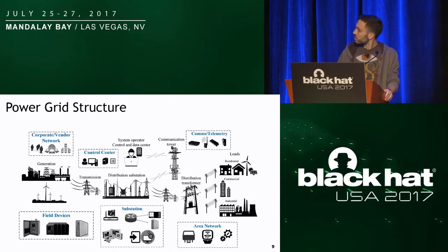The current grid infrastructure is also equipped with cyber systems nowadays that aim to improve the reliability and the efficiency of the grid. These systems include, among others, communication networks, control automation systems, and the so-called intelligent electronic devices that exist in various parts of the grid. They have integrated protection and control functions and communication capabilities for remote operations. Also, these multifunction devices observe the state of the system, make educated decisions, and then take actions in order to preserve the stability and the performance of the system.